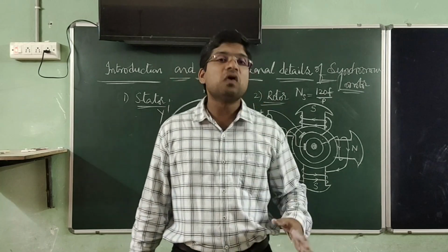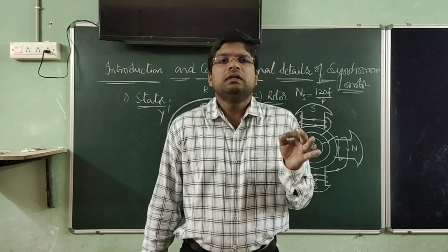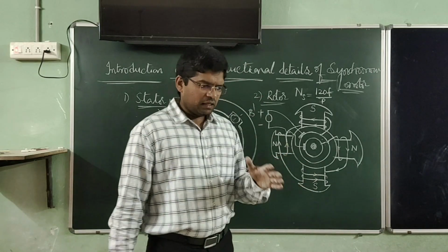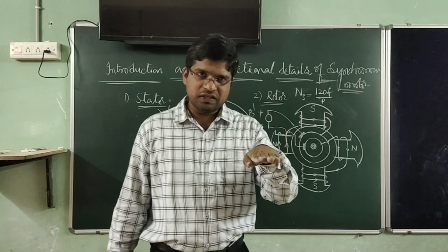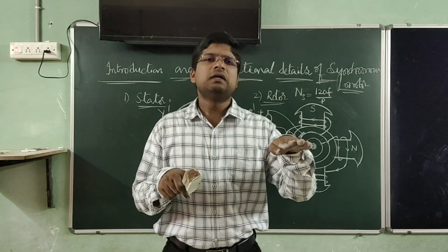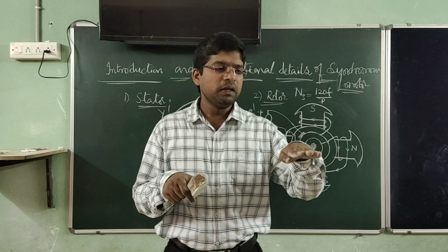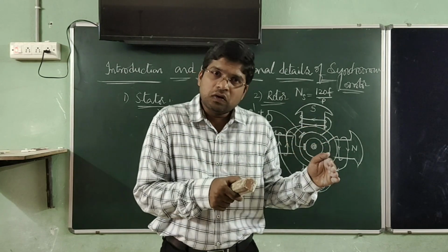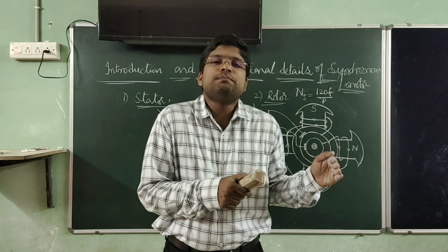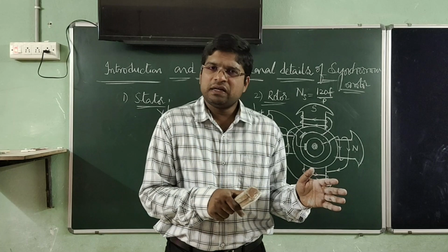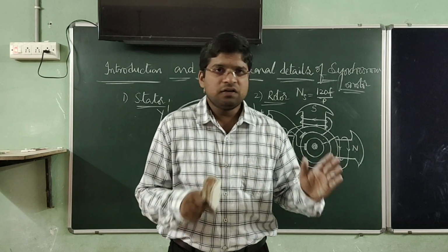So that is a very important point we need to remember for the synchronous motor. That is why synchronous motor is a constant speed motor irrespective of the loads. If it is not rotating at synchronous speed, then there is no developed torque in synchronous motor. The motor will fail to rotate and finally slows down and gets stopped.